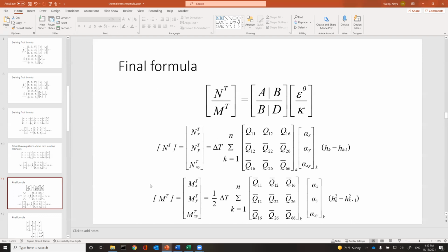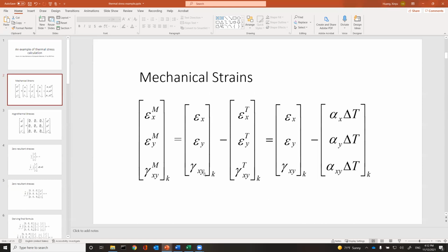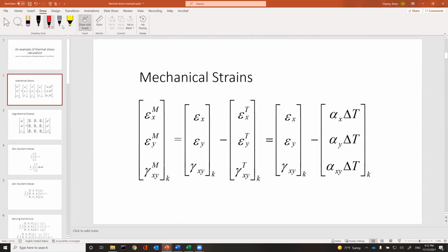And then the thermal load here is basically calculated as such. It is calculated very similar to your CLT code. You sum over all layers, k equal to 1 to N, delta T times Q bar multiplied by your thermal expansion in each lamina and thickness, and this is a bending. So you need to program these two into your code to get this vector NT and this vector MT. Then you plug NT and MT over here to solve for this thermally induced warping and stretching. And from thermally induced warping and stretching, you get total strain. Total strain is this strain right here.